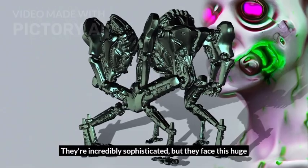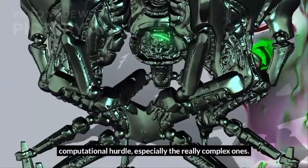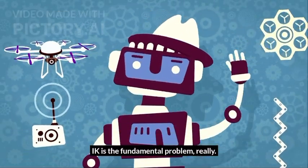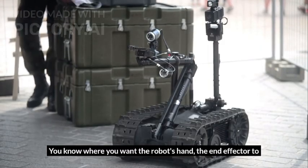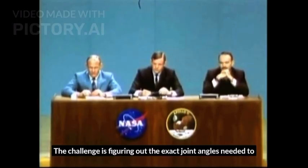They're incredibly sophisticated, but they face this huge computational hurdle, especially the really complex ones. It's called inverse kinematics, or IK. IK is the fundamental problem, really. You know where you want the robot's hand, the end effector, to be, its position, its orientation. The challenge is figuring out the exact joint angles needed to get it there.